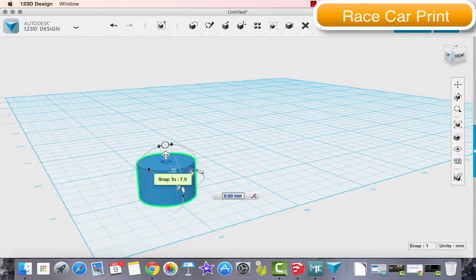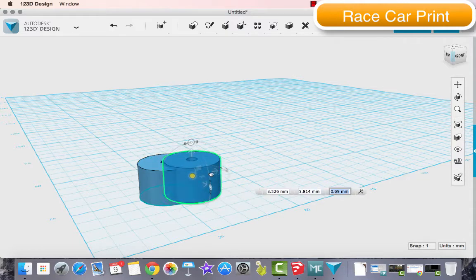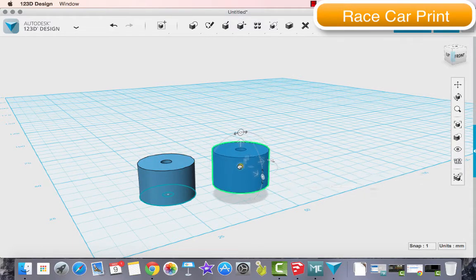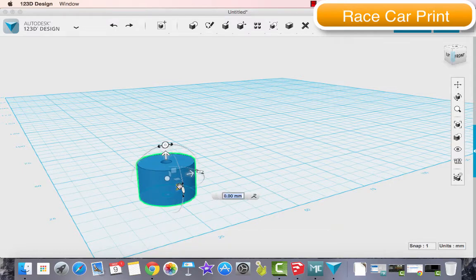And now I want to show you this. So if I click and I drag it and I try to adjust it over, you should see that there's a shadow down here. This means that it's not sitting on my grid. Instead of clicking and dragging on this dot, what I'm going to do instead is I'm going to pull it along an axis.